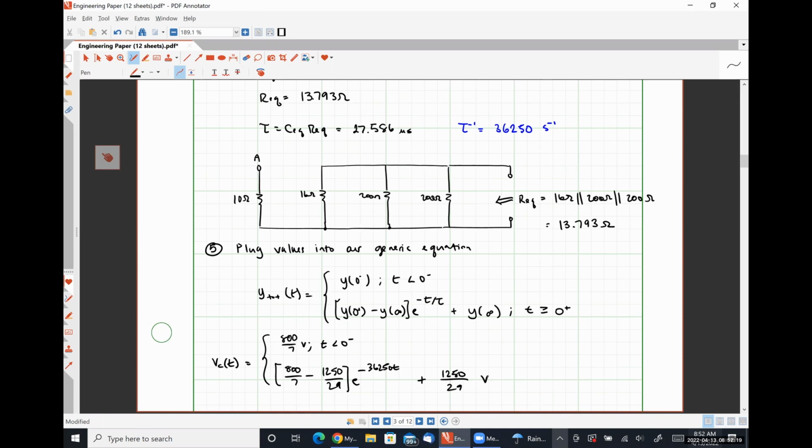We have developed a new kind of catch-all general equation that we can use for both total response problems and natural response problems if we cannot easily identify which one we're dealing with. And we have worked an example explicitly with a capacitor in it because I didn't get a chance to do that on Monday, and shown that at t equals 0 plus, you treat capacitors like ideal voltage sources having the same polarity and magnitude as the capacitor voltage at t equals 0 minus.